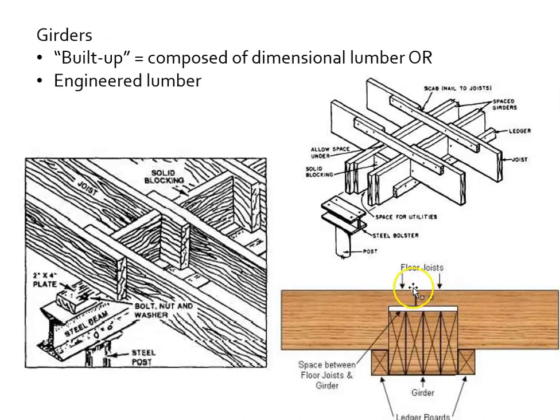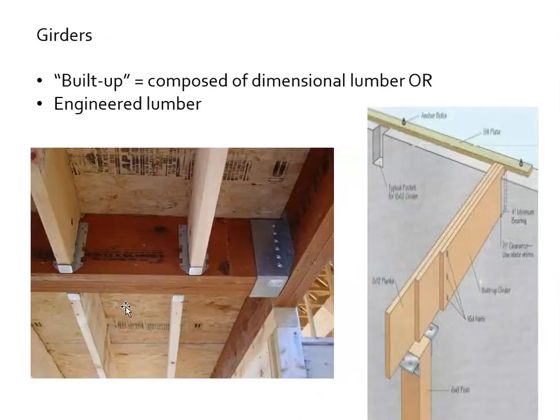Notching a joist like that, again, is a lot of work and not common. Definitely not these days. You'd avoid that. Between the labor and creating a weakness in the joist, there's really no reason for that these days. So this is the most common of this group. And here, this is really what it would look like today.